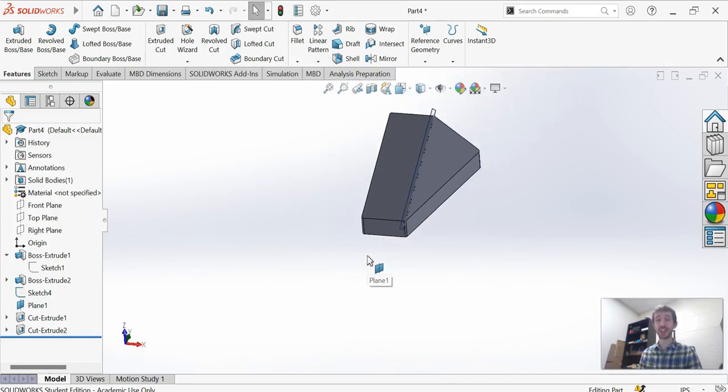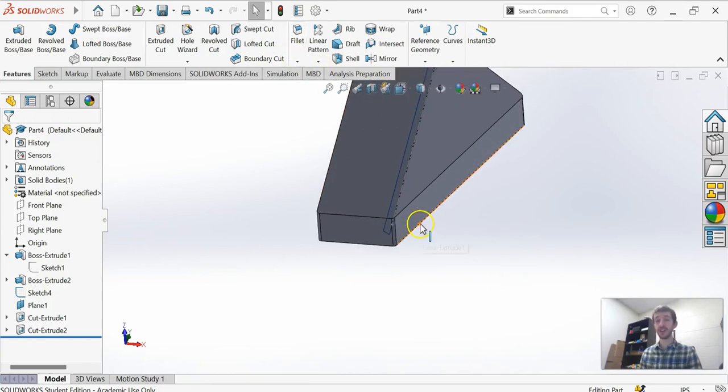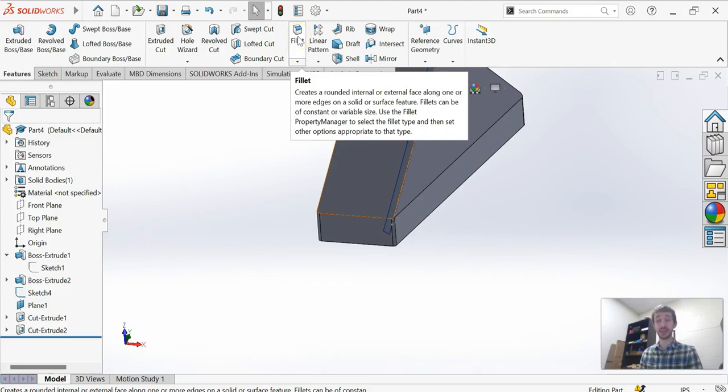I hope you don't. So rather than taking all that time to round every edge individually, go ahead and just use the fillet tool. Now as a note, it's okay to round it from the beginning. Like if I had made my sketch better, I could have avoided having to round this edge right here. But some features would have been harder to make. Honestly, filleting at the end is usually simpler.